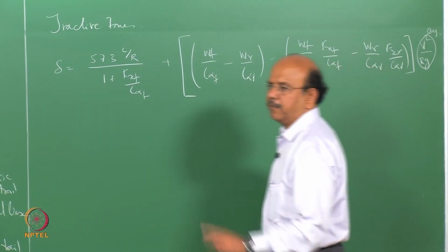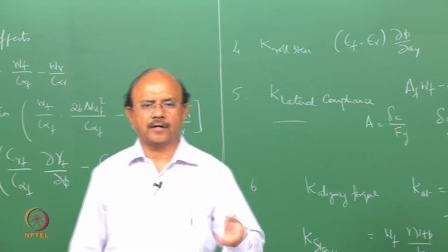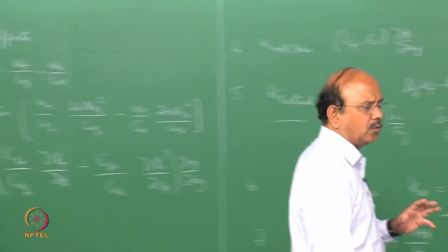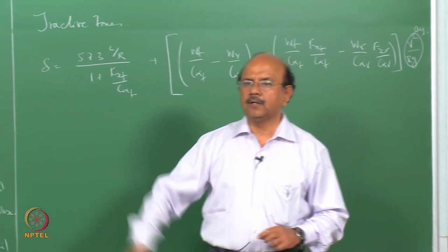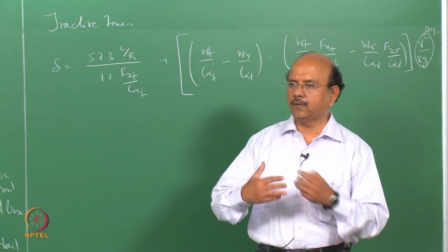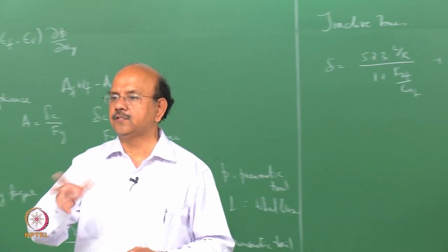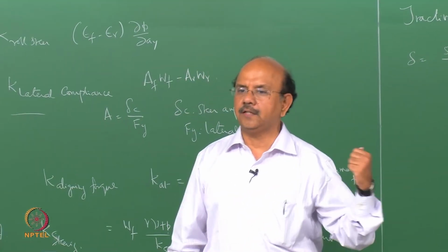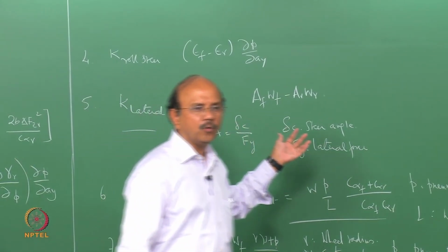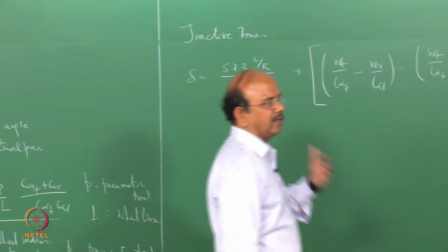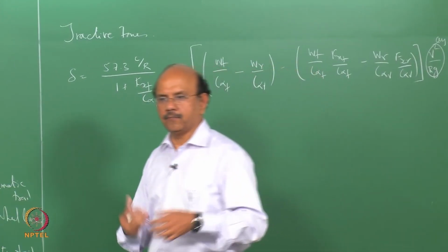And lastly, the two things which we have left out. One is there is a load transfer to the front because of acceleration, deceleration, and so on. We mentioned that. We have not taken that into account like what we had done for the rear and front due to roll. Okay, here this is due to pitch. Unfortunately, the model which we have won't be able to take that into account. So you have to go to a much more detailed model if you have to look at how load transfer is going to have an effect on this.